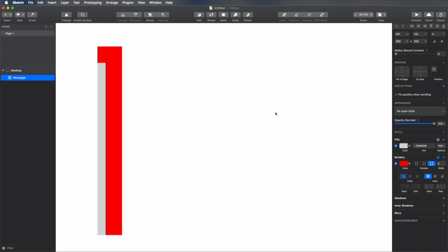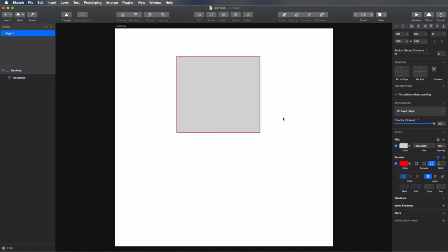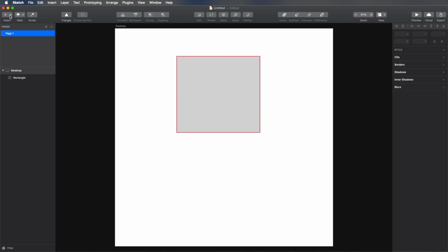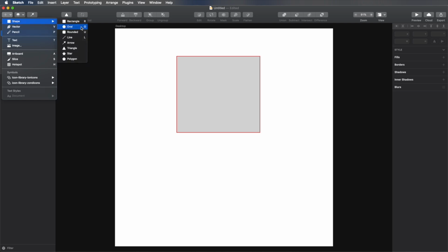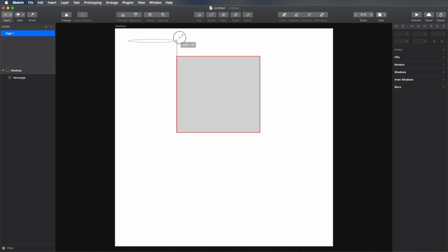So that's how you can create a simple shape. As I mentioned, there are a couple of shapes you can choose from. This was a rectangle, but you can choose an oval tool. This will create either an ellipse, or if you hold down Shift while dragging, it will make sure the width and height are the same. So you draw a perfect circle.